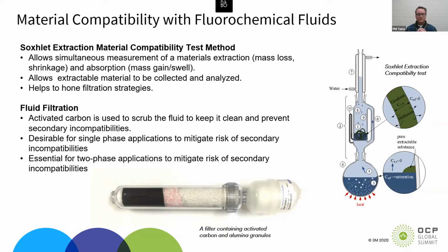In practice, it's less important in single phase applications, and I can't honestly think of a single phase user that rigorously filters their fluid. But it's extremely important for two-phase applications for the reasons I mentioned. The oils and contaminants can distill out on boiling surfaces and affect thermal performance at the very least. And that's where I'll wrap up.